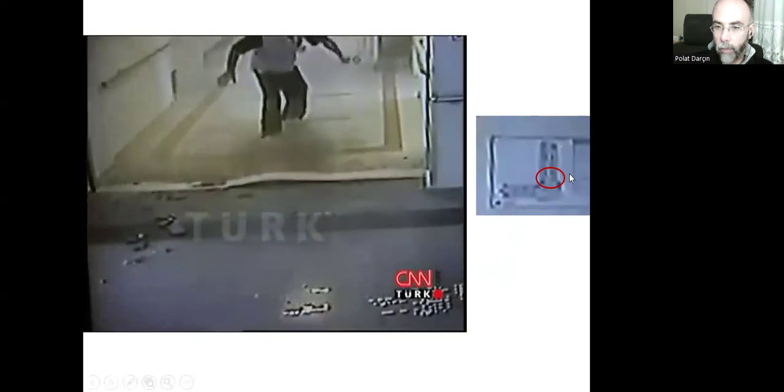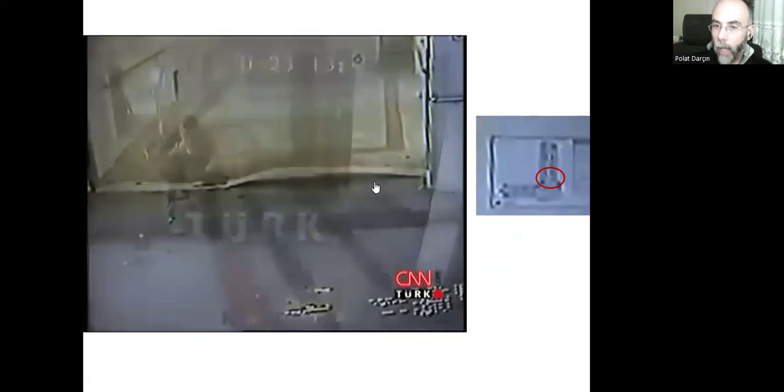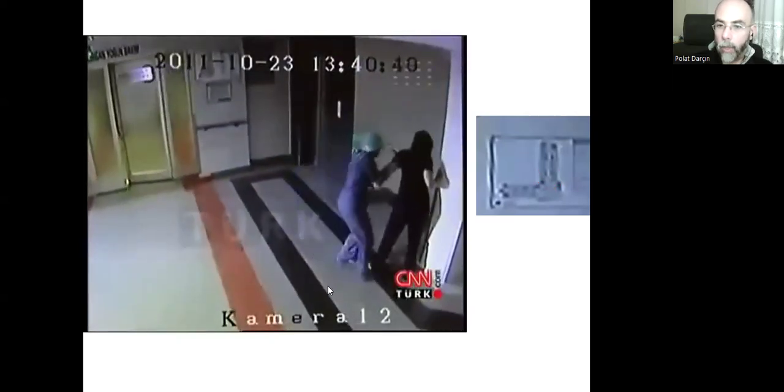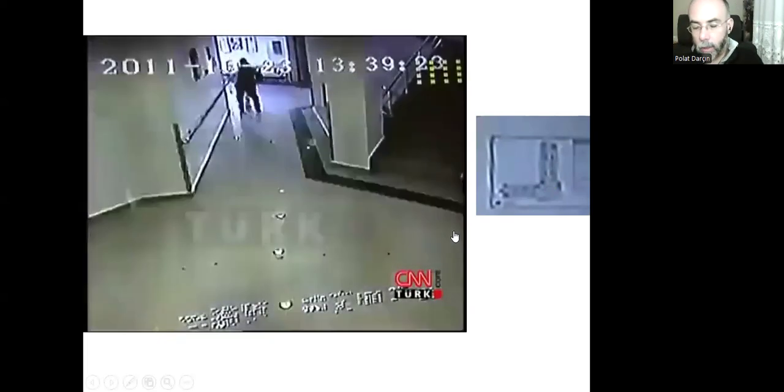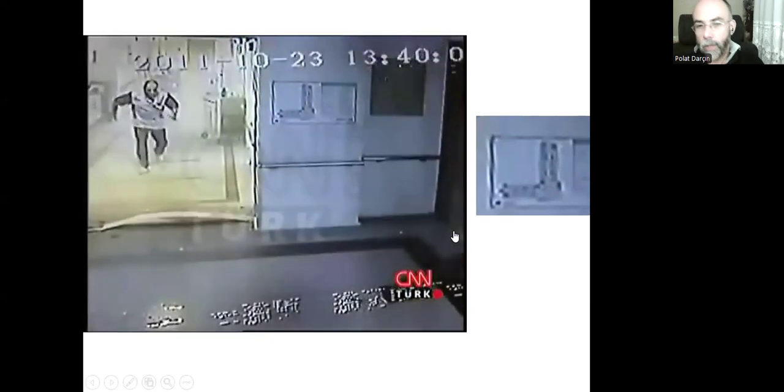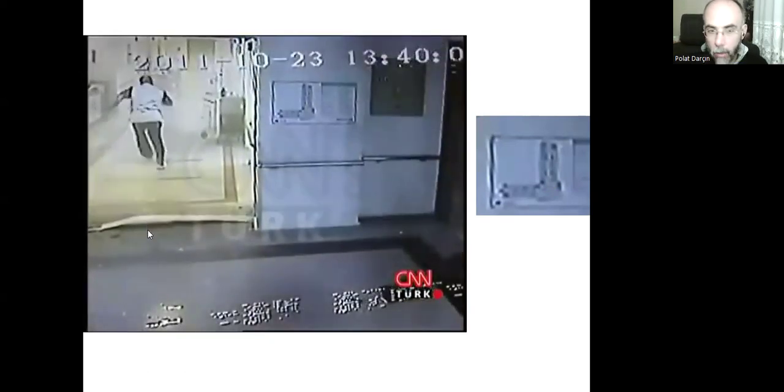As you can see, this lighter part sways more, and this heavier part doesn't want to sway, and we have a seismic gap there. With the help of the seismic gap, there's this piece that closes the gap. You can see the difference between the sway, because it's elevated so much.